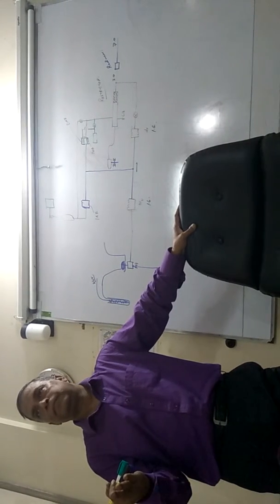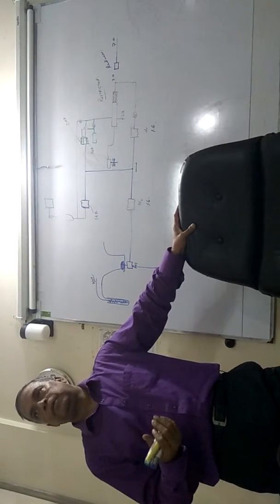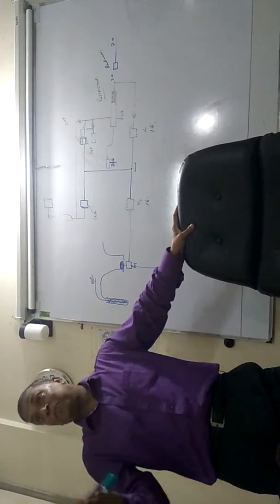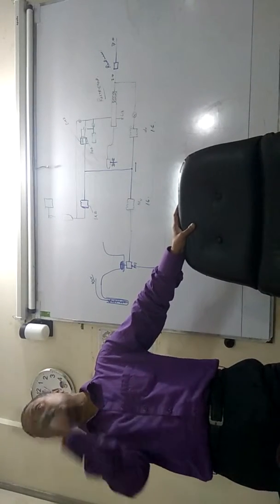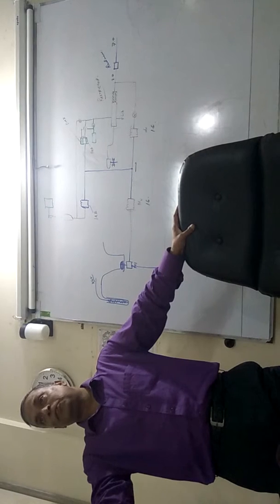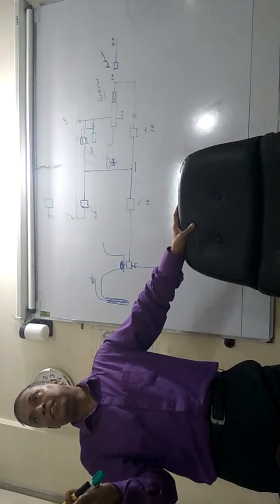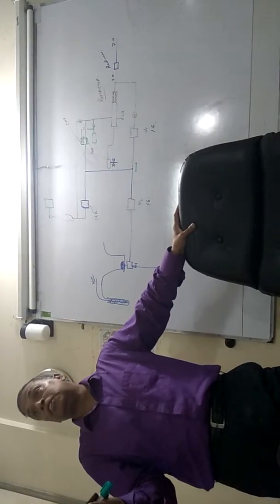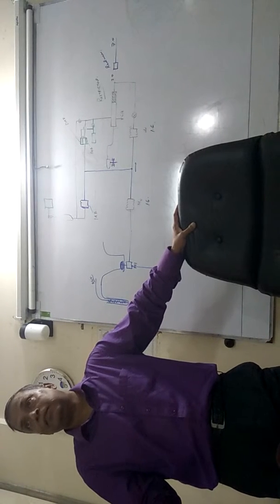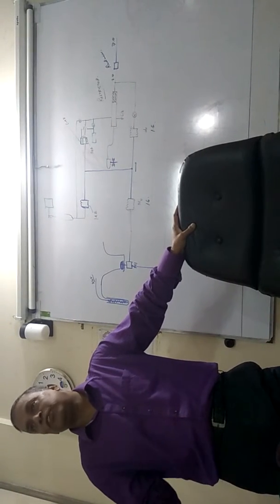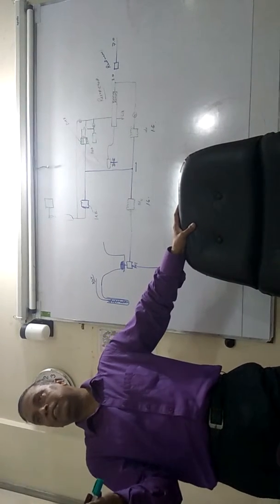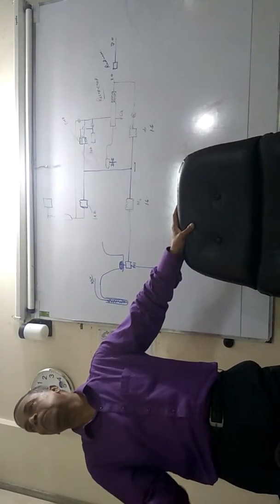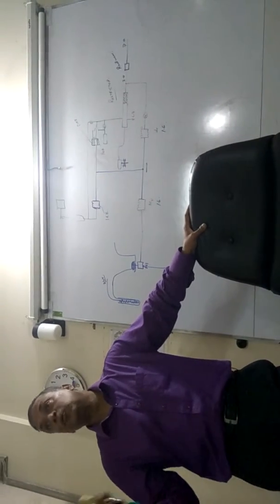So error and deviation is the same, isn't it? It's the same, yes. And offset is the sustained deviation. Offset is also the difference between measured value and desired value. You have to say that. Yes? And what about deviation? That is corrected. What about offset? It's not able to get corrected. Right? That is the difference. One is usually corrected, the other one is corrected when integral action is there. Otherwise, it remains there. And then we call it an offset.